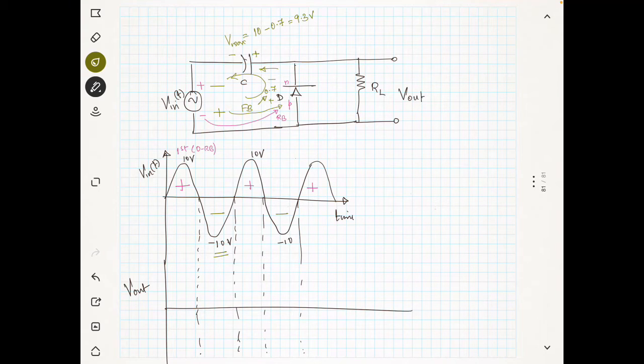So you will be getting 9.3 volt across the capacitor with this polarity as shown here in the figure. The polarity will be like this. So the capacitor charging is happening. You see here, during the first cycle the diode was reverse biased, and in the second cycle the capacitor charges.